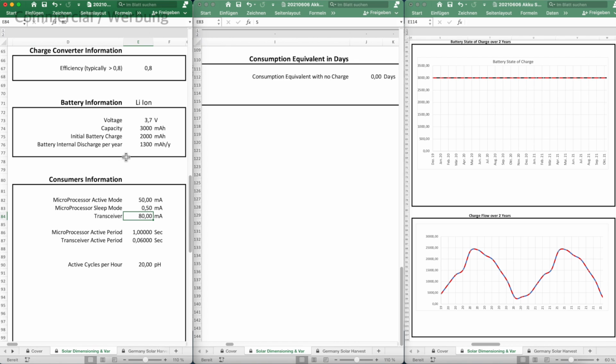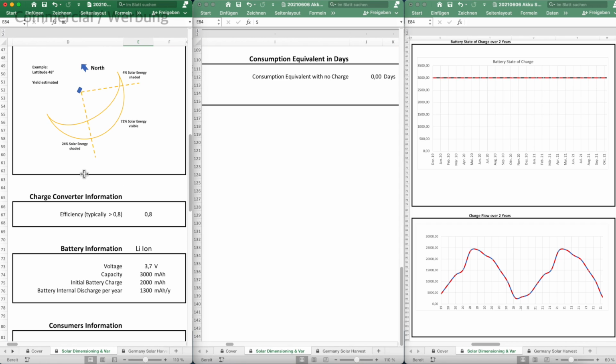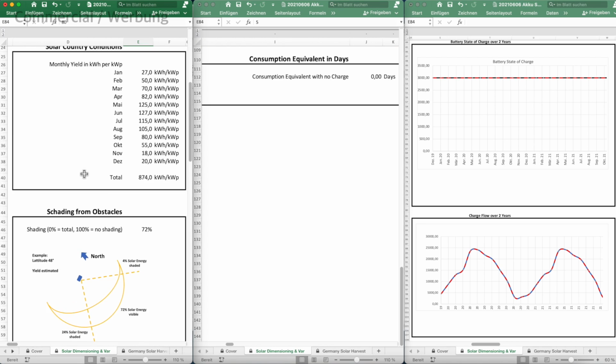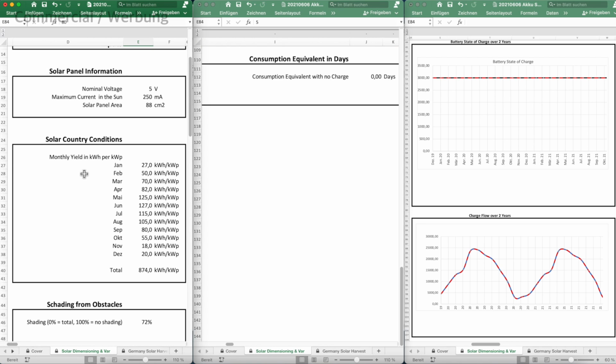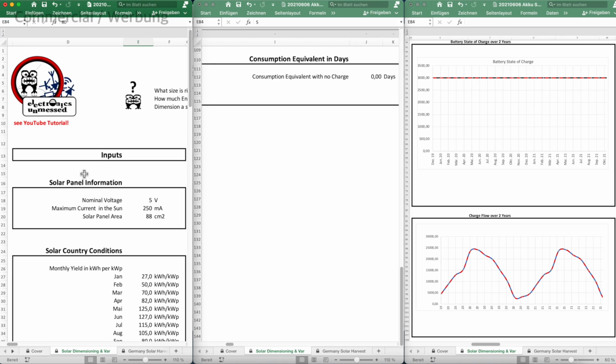Good low power boards can go down to about 400 microamperes or much less in the deep sleep mode. The energy budgets are showing us that we are more than good now for the whole year with this. Now let us see which additional degrees of freedom this is giving us.